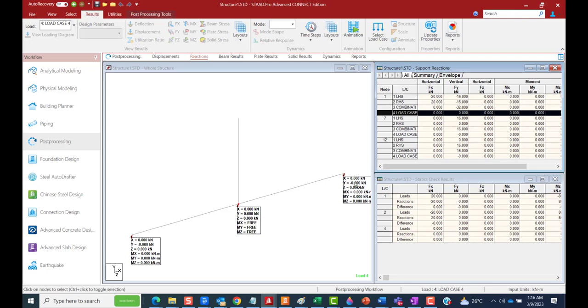I've seen several users who straight away use the load combination, come back to us and ask why STAAD is giving such unusual, out-of-proportion results. But this is the main fact. They make the mistake, and they use the design based on this erroneous and misleading result.